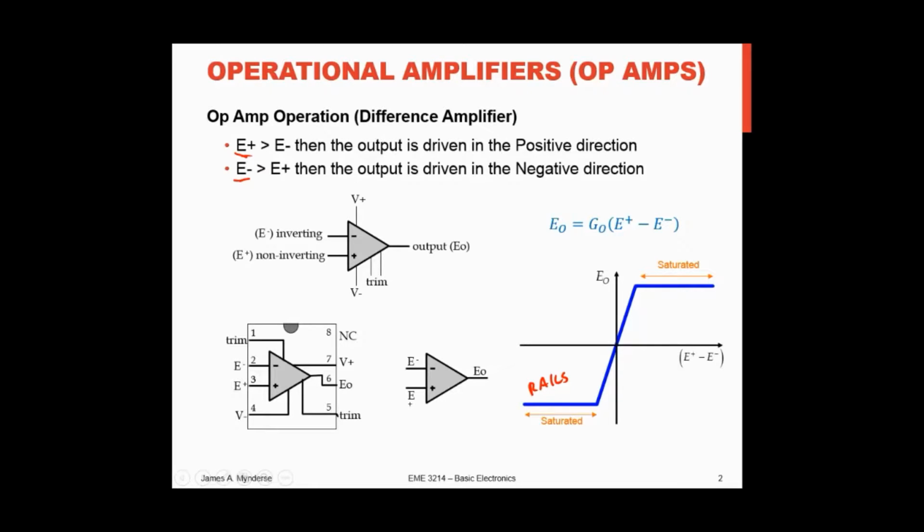But normally when we're drawing it for this class and in simple circuits, we'll ignore a lot of those details and we'll just draw it using this triangle, which is the symbol for an operational amp. The negative input, the positive input, and an output. And we will typically just work with that and assume that the physical limitations don't exist, because we'll make assumptions that we are using an ideal op-amp, which is on the next slide.